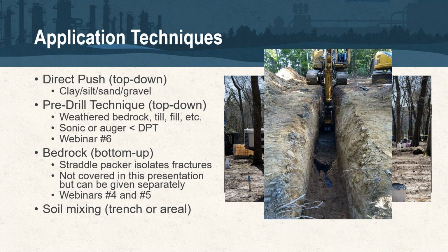And then lastly, if you ever have access to be able to soil mix really any technology in, and so ours fit into that. Anytime you can direct mix it in with either installing a trench like what you see here, this was a site in Pennsylvania that I worked on, or if you were doing an excavation and you want to mix in one of these technologies into the smear zone, you'll never get better distribution than that. And so it's something that I always recommend looking at if it's available to you.